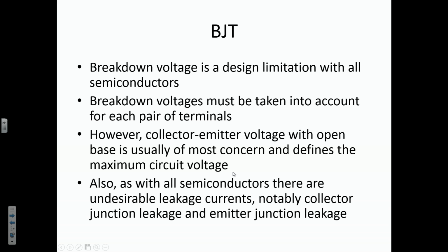Now, we talked also about the breakdown voltage in semiconductors last time, and basically that was something that we tried to avoid except in Zener diodes. The breakdown voltage is a design limitation with all semiconductors. Breakdown voltages must be accounted for each pair of terminals. Okay, so we don't want to exceed the voltage and destroy the transistor. However, collector emitter voltage with an open base is usually of most concern and defines the maximum circuit voltage.